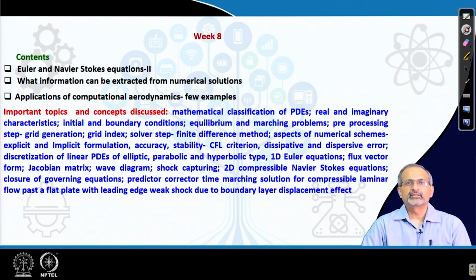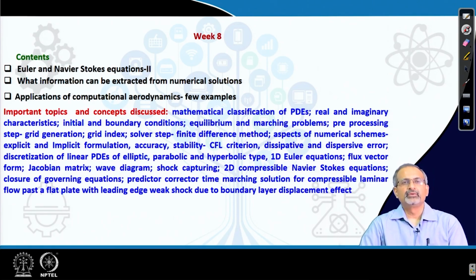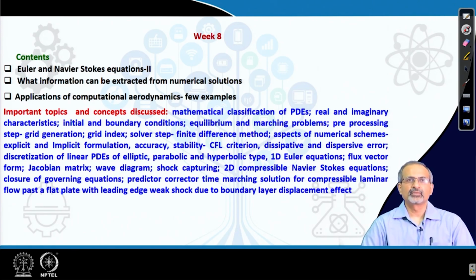And then we discussed the pre-processing step in detail through grid generation, and we introduced the concept of grid indices. Then in the solver step, we discussed the finite difference method, and then aspects of numerical schemes like explicit and implicit formulation, accuracy, and stability, where we discussed briefly the CFL criterion, and different kinds of errors like dissipative and dispersive error. Discretization of some linear partial differential equations of the elliptic, parabolic and hyperbolic category was discussed, and then we got